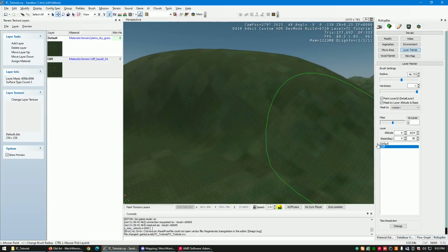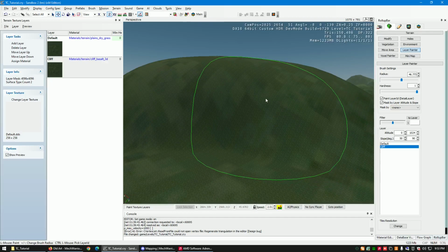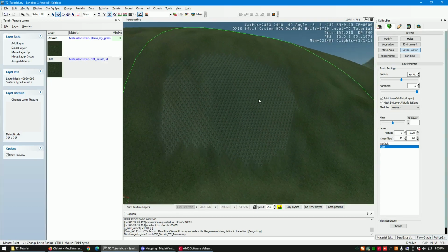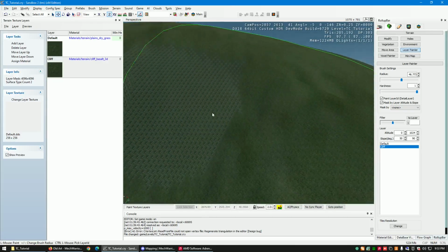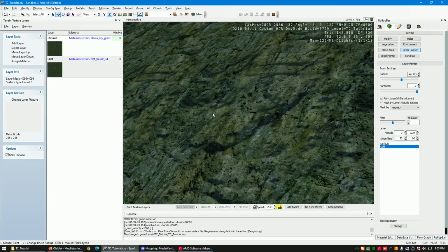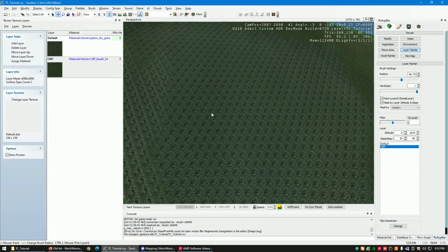For example, since we've selected a cliff, we want to have the cliff only on something that's relatively angled. So let's say 50 degrees to 90 degrees. You enter slope from 50 to 90, and that means it'll only apply the texture if the slope is at that angle. And sure enough, if we click on it, well, there's your not very pretty texture. That's pretty terrible, actually. If you look at it, it's very, very detailed and it's very patterny. So how do we fix that?